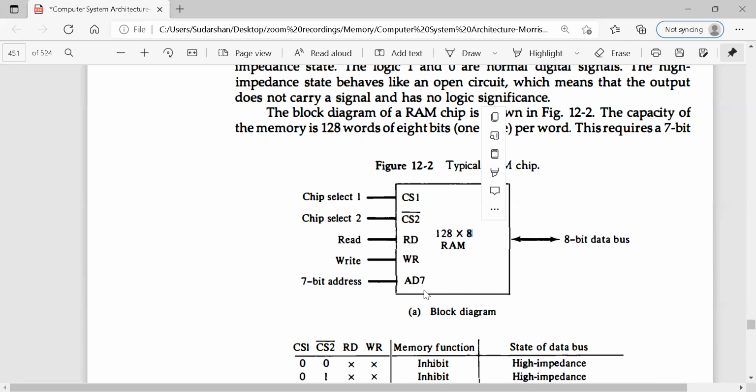You know, the address bus is unidirectional. It always goes from CPU to memory. To identify a location, first use the address bus, place the storage location address on the address bus. It is transferred from CPU to memory. And then the data bus is bidirectional. We know pretty well it can flow in both directions, either from memory to CPU in the case of a reading operation, and CPU to memory in the case of a writing operation.